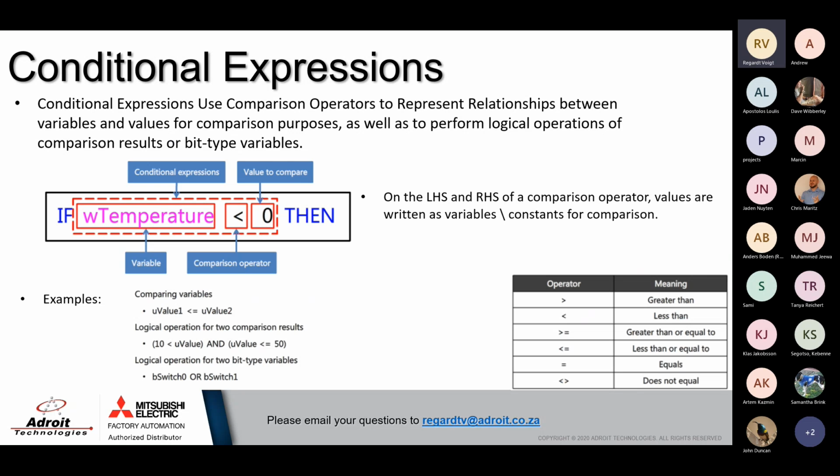You also have your comparator operators. So you've got your comparators, converters, your arithmetic, your logic operators, same as with your function block diagrams as well as your ladder diagram programming, which can be used in conjunction with your sequential function chart languages. So yeah, it's the classic basic comparison operators that are used: equal, not equal to, greater than and less than operators.